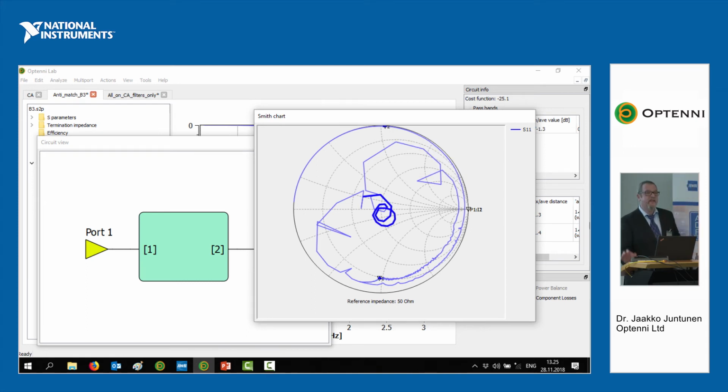We see that it's rejecting okay, especially band 20. It's very close to the edge of the Smith chart, but the phases are relatively arbitrary unless they are designed up front. In my case, I just took the filter that I could get. So now the challenge is to have a good match for band 3, while simultaneously mapping band 20 and band 7 to open circuits. Then we have a structure that is invisible to those other bands.